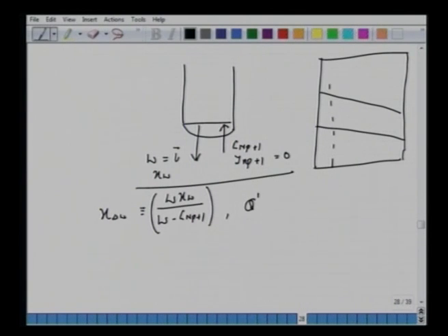This stream will also have a modified heat energy leaving, which would be W hW. So this is the heat leaving the bottom plate, minus what we add here, G_{NP+1} h G_{NP+1}. This would be the enthalpy of the saturated steam which goes into the column. The net molar flow rate is now W minus G_{NP+1}.